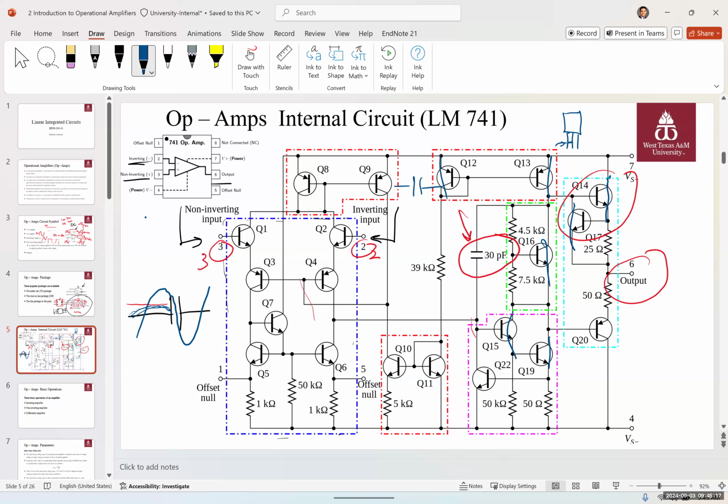So transistors have what we call a band, the frequency response, and if the frequency goes too high, the transistor technically becomes like a short circuit, because now you have a capacitor between these two terminals or the pins of the transistors, and at a high frequency, the current would just jump through the terminals, and you won't have any transistor at all.